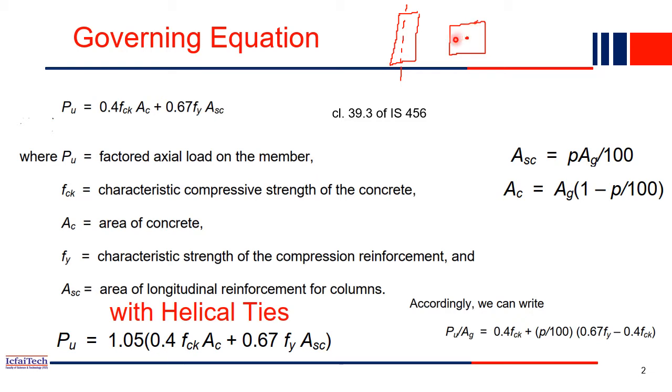But we have seen in the last lecture also, it is very difficult to construct a building and a column where the loads are acting just at the axis point. Practically we can't make it so; all columns will have some amount of eccentricity. Whatever it may be, small or large, there will always be some amount of eccentricity. So that's why our code has specified that even in the case of an axially loaded column, we should consider a minimum eccentricity.